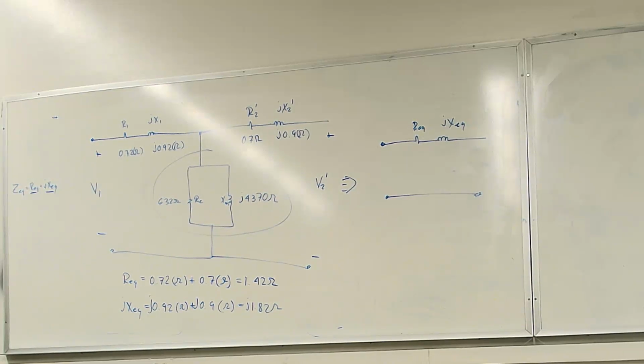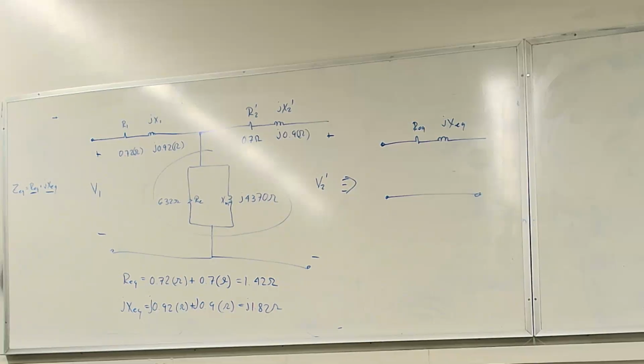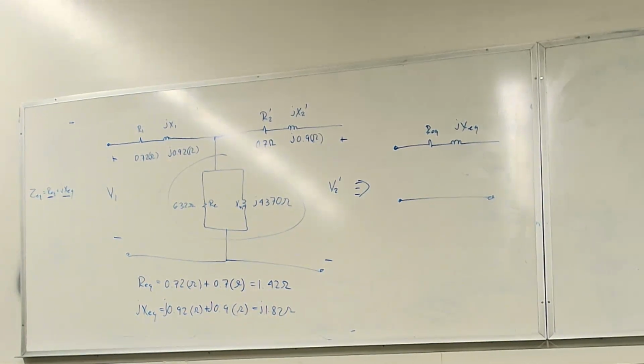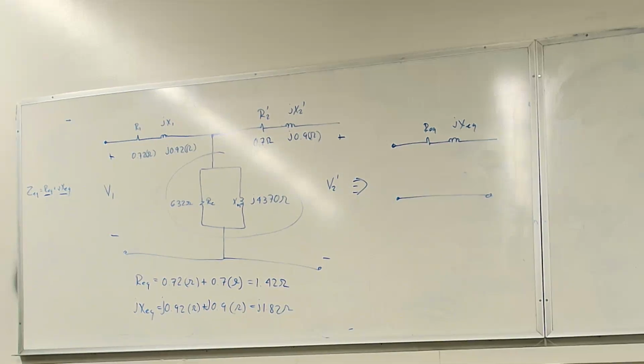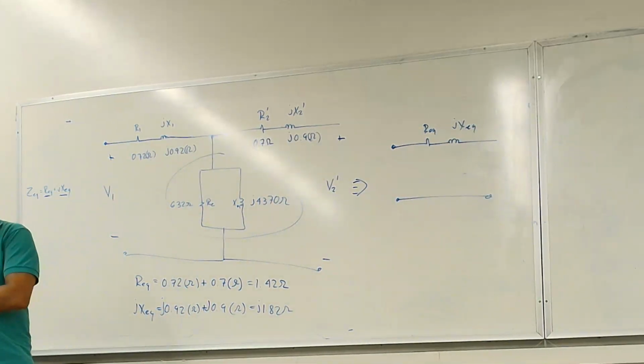But you need to put that information on your short circuit analysis or your motor starting or your load flow analysis. You need those impedances. There is such a thing as generic values, and I'll give you a table of generic values that you can use. The problem with generic values is that they're generic values, right? So they're not as accurate, but in some cases good enough for the analysis that you're doing. So either you get it from the manufacturer or you have to do some testing in the lab.